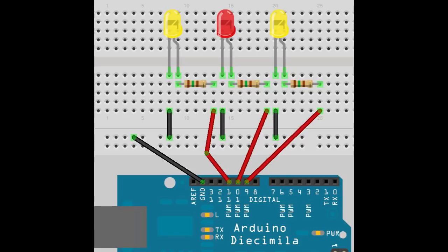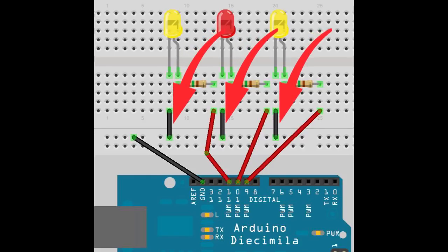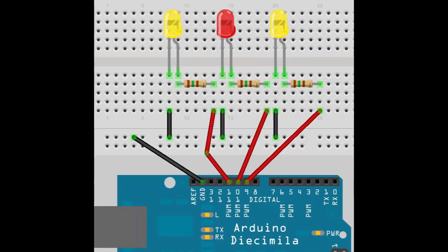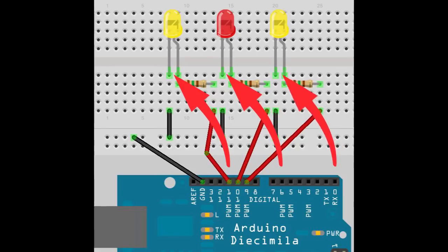the Arduino. As we move to the right, you'll notice that there are 3 gray lines or 3 jumpers that connect that negative horizontal line that's connected to the ground into the work area. And if we work our way straight vertically up, you'll notice that those gray wires are connected through the work area to the negative side of each of the 3 LEDs, or the shorter or straight diode.